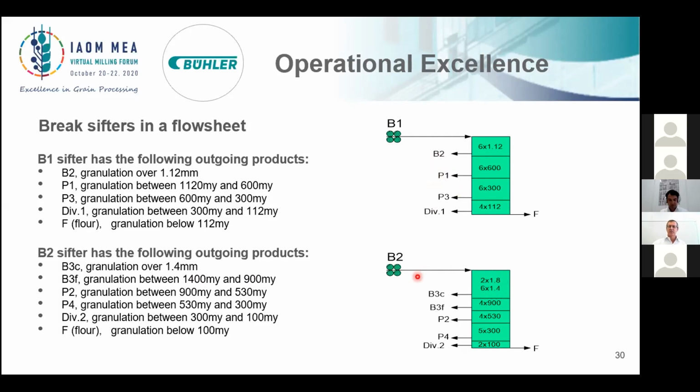It could be this mill was designed for a hard wheat, but then changed to semi-hard. So 1800 micron helps to faster separate the granulation below, and it doesn't mean that you mix the product, but you have a faster release of the semolina below, but after that you go to 1400 because that's your target range.